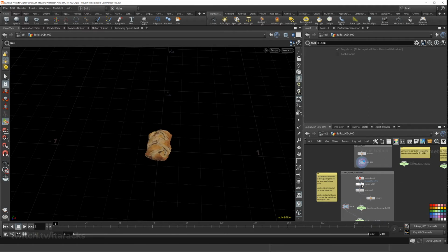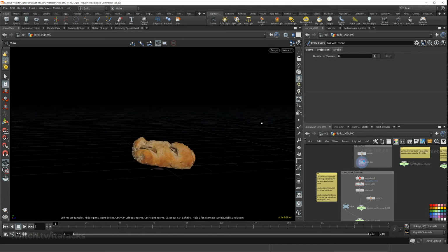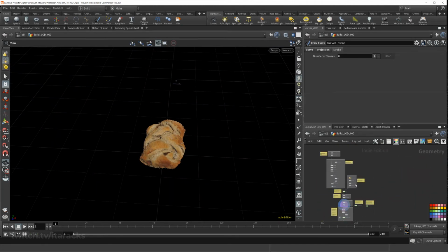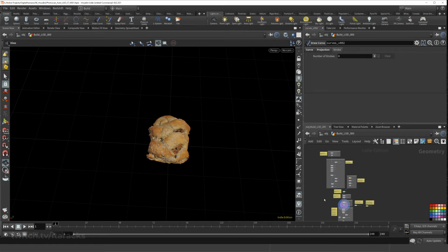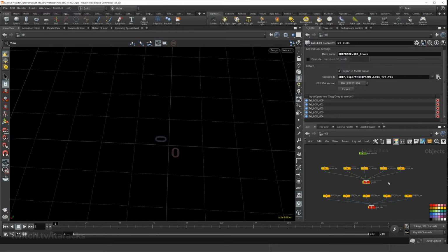So if we go back up here, we can also go in here and clear that if you want to start again. So this is the highest resolution of your scan, and everything after this will be based off this. So that's kind of why this has all the control in here. If you're using a photo scan, you definitely want to make sure that everything looks right at this point, because everything after this will be using this as a reference. From here, you would definitely have to wait for quite a few of the processes to happen. Once you go right away to export, there will be quite a few things that happen. So I also advise, if you want to go check out all of these things, to switch your update to manual, just so that you don't have to cancel or escape out of any of the processes.